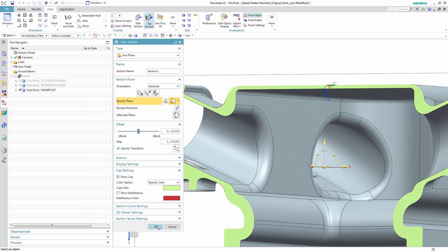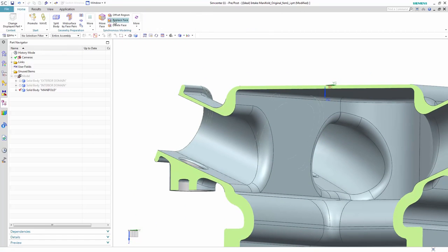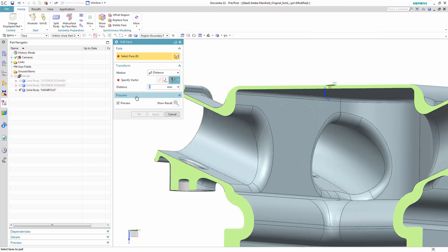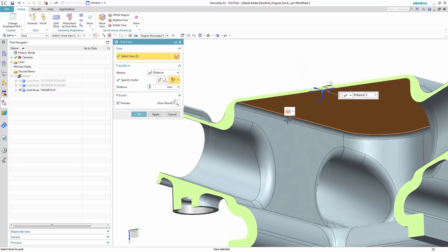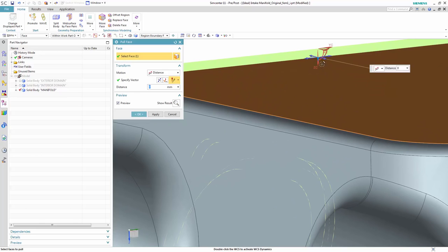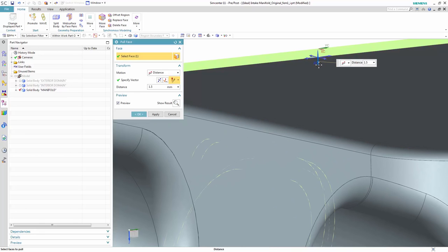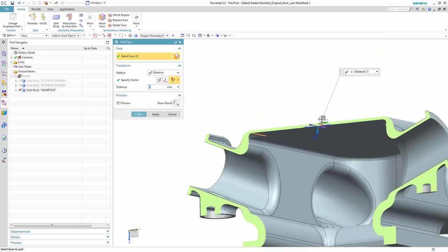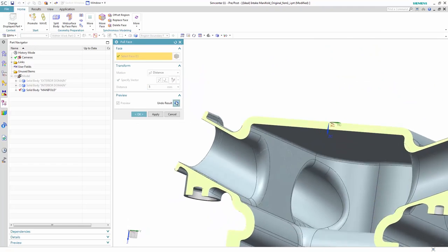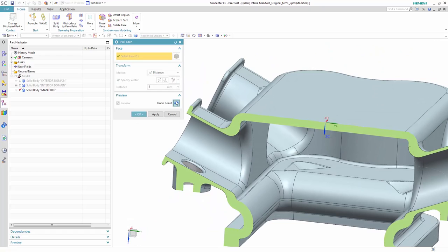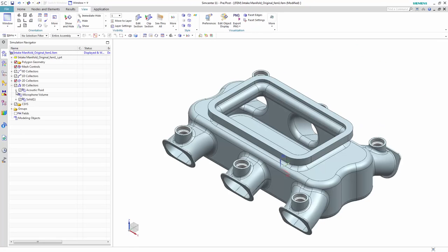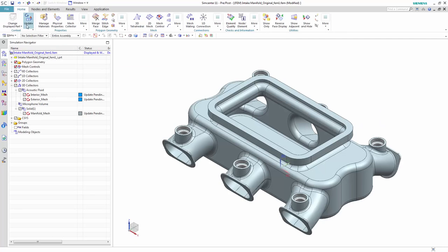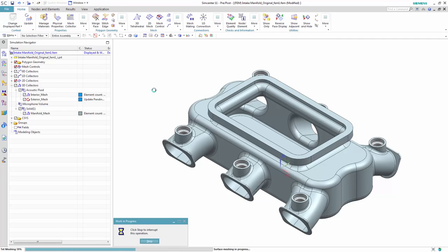of the manifold. One of the strengths of Simcenter 3D is that the analysis model is associated to the underlying geometry. This means you can quickly modify the geometry to test out a new design proposal and update the entire analysis model without having to manually rebuild it each time. This is possible on any geometry from any CAD source. What would otherwise be a cumbersome multi-day workflow in other tools is reduced to just minutes in Simcenter 3D. After modifying the geometry, you can then simply update the meshes and verify that this design change has propagated to the mesh.